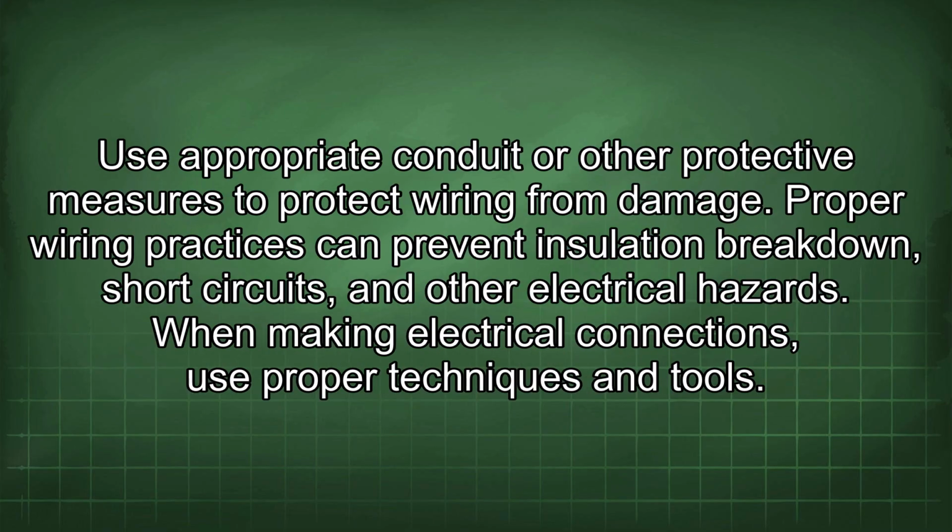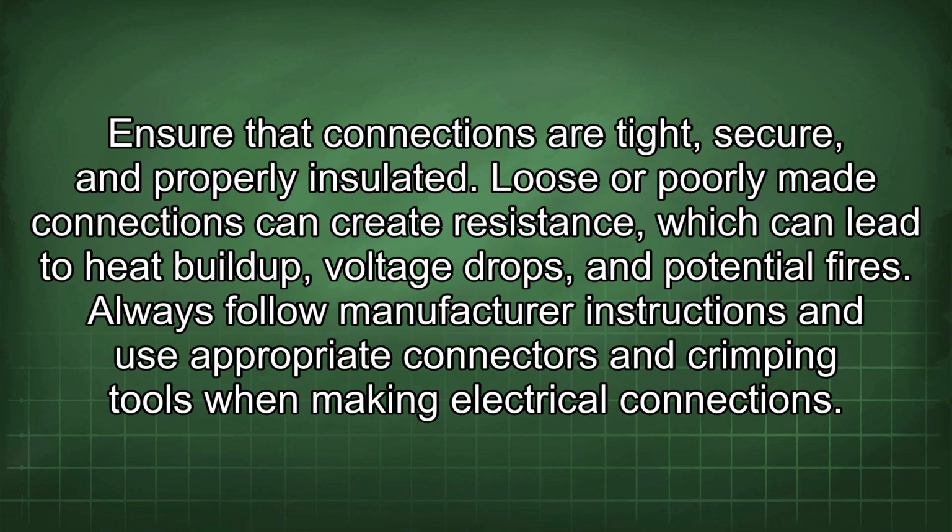Use appropriate conduit or other protective measures to protect wiring from damage. Proper wiring practices can prevent insulation breakdown, short circuits, and other electrical hazards. When making electrical connections, use proper techniques and tools. Ensure that connections are tight, secure, and properly insulated.